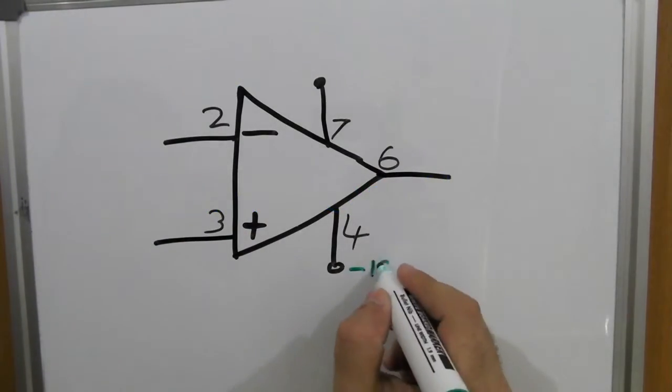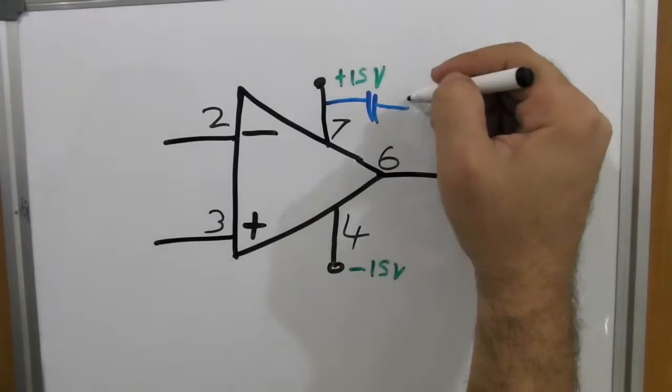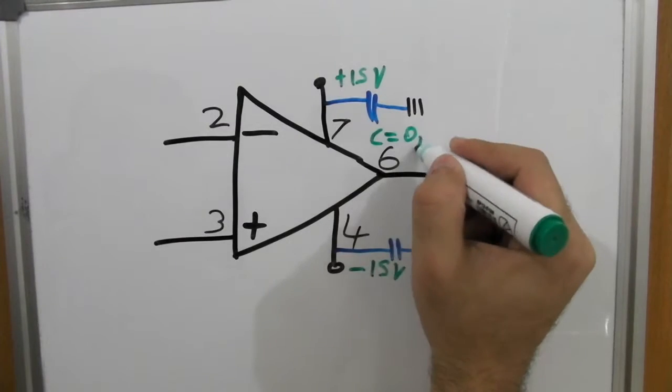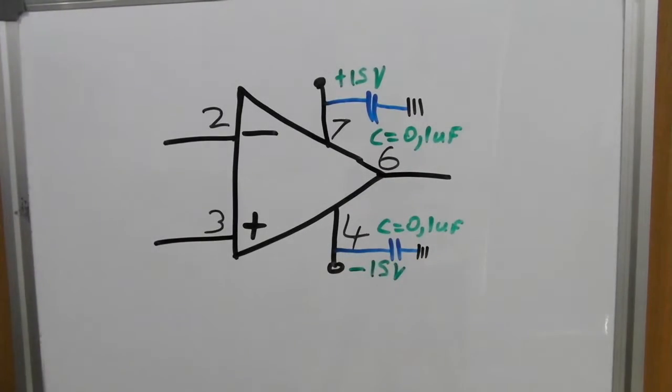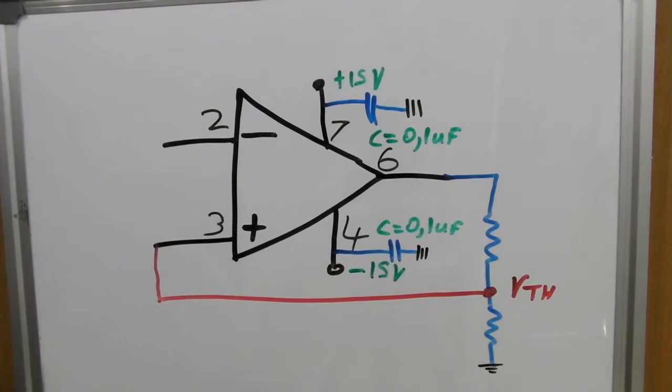Here is a quick look on how to assemble an Astable Oscillator. As you can see, in this assembly, I used 2 extra capacitors. Those capacitors are used in order to avoid parasitic oscillations and reduce noise. They are called voltage smoothing capacitors.